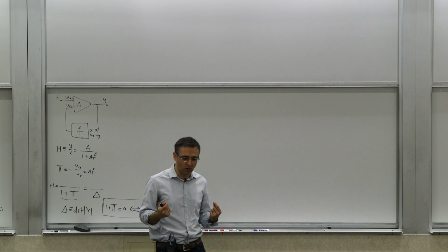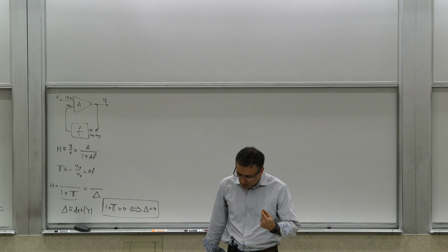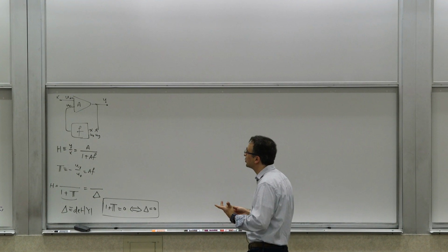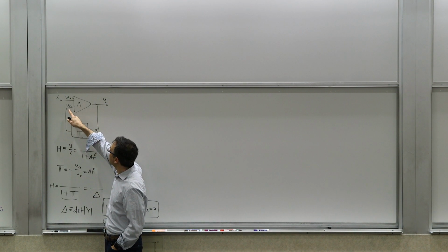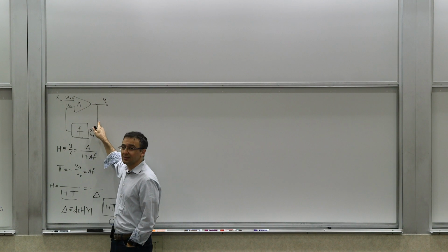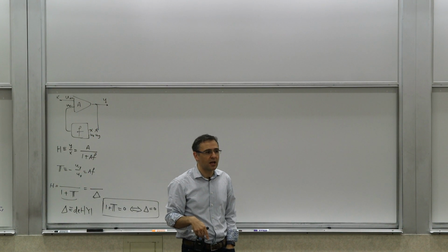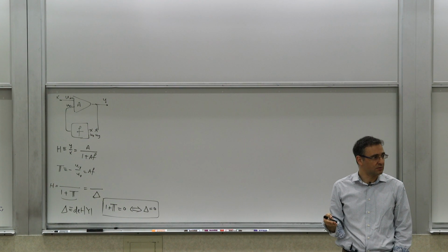So this needs to hold for whatever we define as the ratio. The other thing we want for a loop gain to be meaningful is that it should be an invariant of the loop. It shouldn't matter if you have a single well-defined loop like this. No matter where you cut it and how you cut it, you should get the same result, even for a bilateral loop.